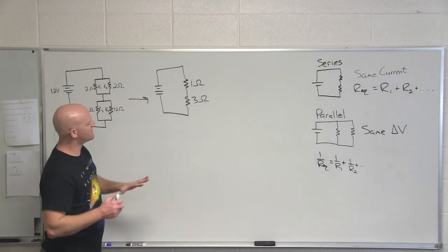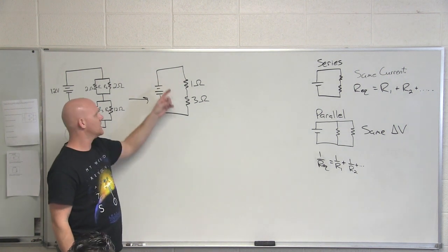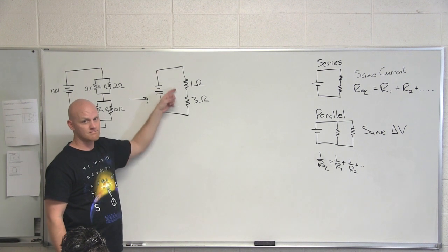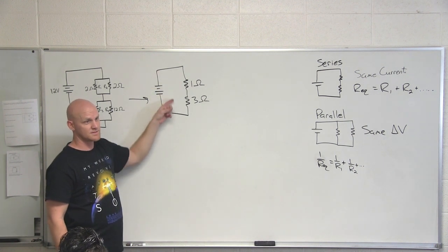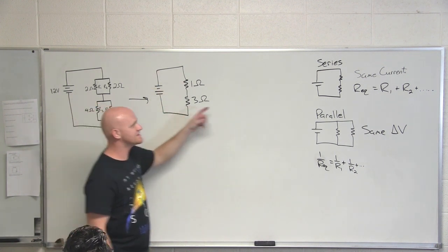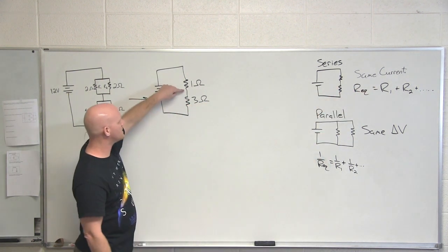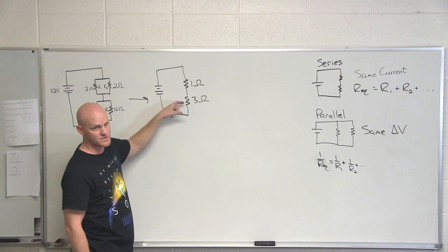Series. They're in series. Before we go there, though, if I look at this diagram here, which of these has more current? 3 ohm. No, 1 ohm. 1 ohm. It's a trick question. 3 ohm. They're in series, which means they have the same current.